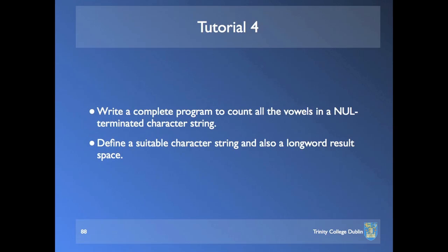Second thing to remember, and this has come up a few times, is that the condition code register has these 5 bits, X, N, Z, V, C. They all have values all the time. If you want to make use of them for something, you have to make sure that they have a value that you're interested in, and that you have previously calculated in a way that you want. It's not that they'll be 0 or that they forget anything.